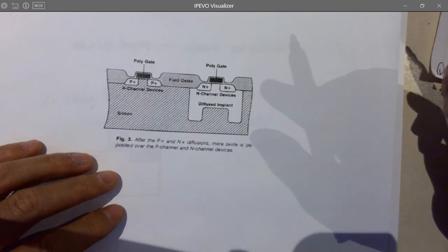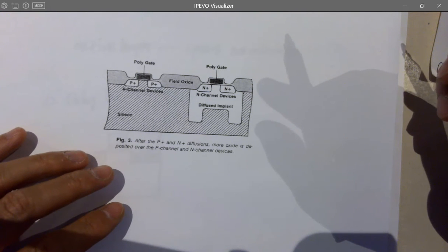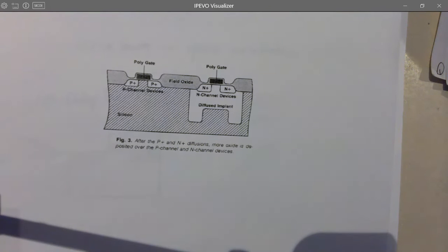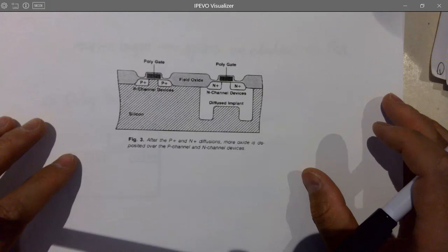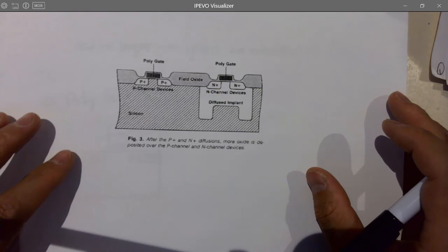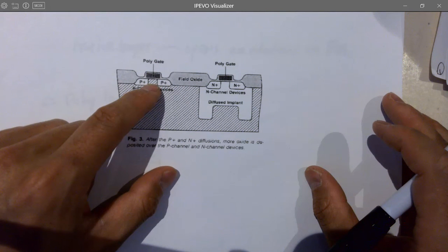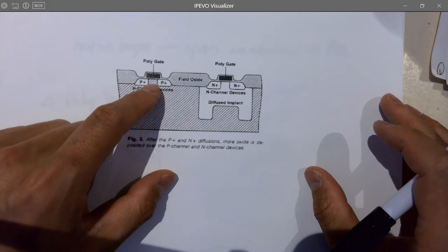So remember the name of MOSFET? What does MOSFET mean? So what is FET? Field effect transistor, right? So what does that mean? It's comparing to BJTs. BJT doesn't have the field effect. It directly dumps current into the junctions. This is the field effect. Why? Because there's an insulator in between the gate and the transistor. It's not directly dumping current into it, so that's why it's less power consuming. That's why it's a better technology to be used. In all the low power designs, you don't want to use a lot of BJTs, you want to use MOSFETs.